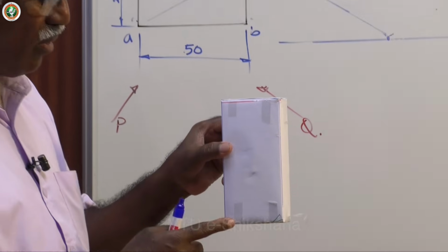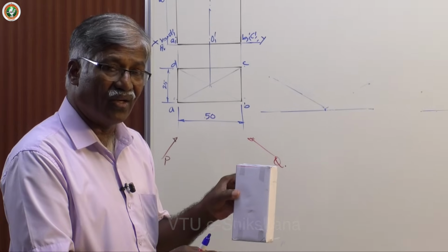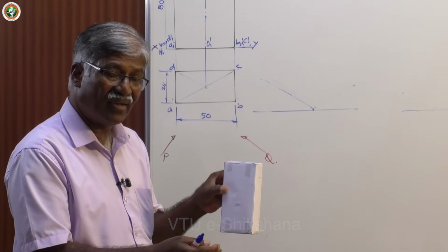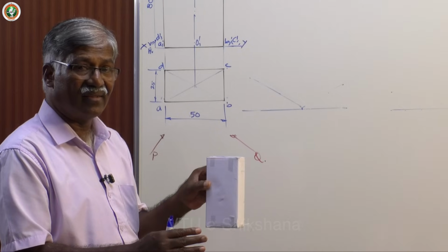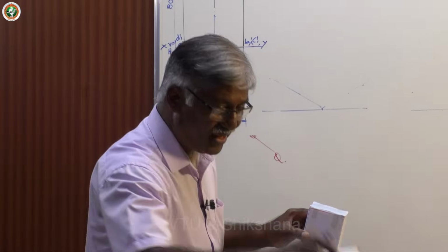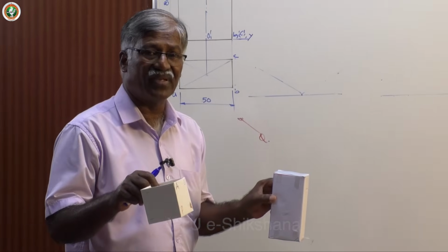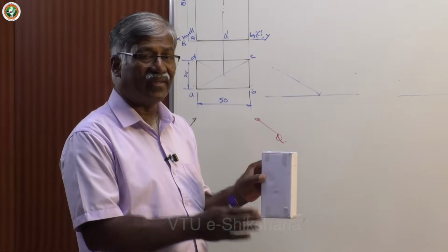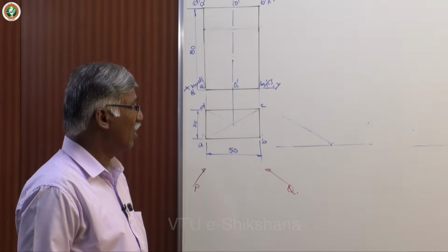In isometric view, all sides which are parallel to VP and perpendicular to VP and also perpendicular to HP are on either a 30-degree line or a vertical line, none other than that. Only in the case of standard solids, I mean square prism and rectangular prism, and also the limiting case of square prism, the cube, in these types of problems all the edges are on 30-degree lines or vertical lines. Now let me start working the isometric view of this.